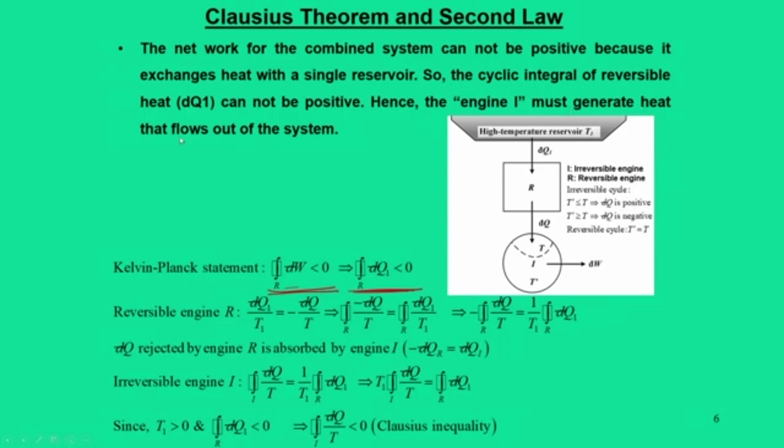the ds sits here, and second it is also here, there is a negative sign here. For this equation, because in this case it is greater than 0, when both are subtracted, this will be greater than 0. Interestingly, if you look at it by definition, ds in a reversible process from i to f, the same reversible process, the reversible term will get cancelled, and the irreversible term will remain. When you only take the irreversible process, we end up with ds always greater than dq by T from i to f, that means greater than the cyclic integral.